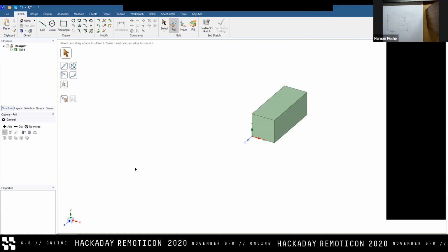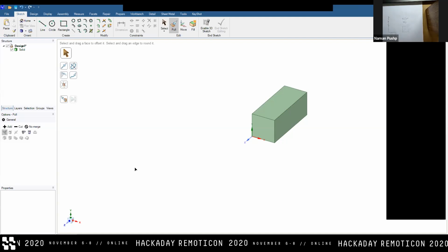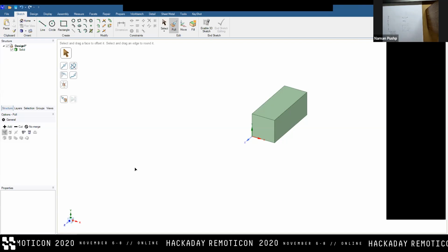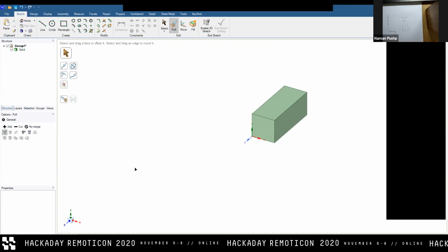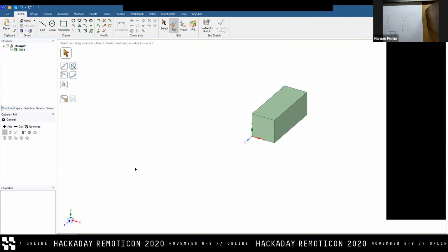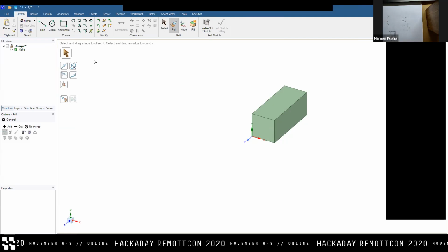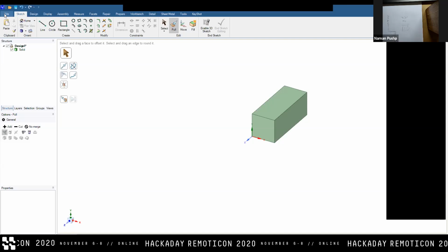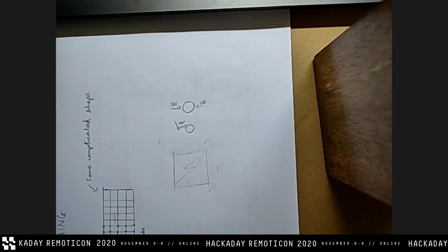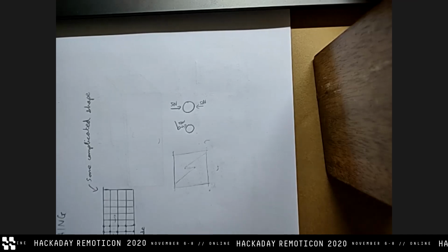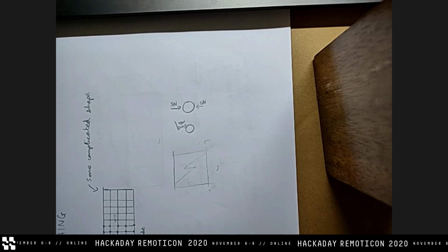But if you're using a CAD software that can't do simulations, one thing I learned the hard way, by spending an entire day completely failing to mesh, is that when you're exporting, please always export in .iges. Let me even type that out, because it's quite important. So it's .iges file.